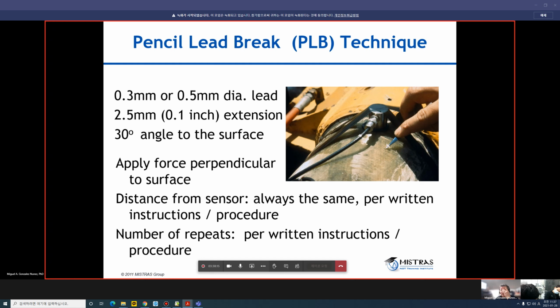So 80 decibel, because it depends on the many parameters of the system, right? It depends on your coupling. Yeah, and gain value or many. No, the gain, you don't use the gain. What do you mean? The only parameter that you use in acoustic emission is the threshold.